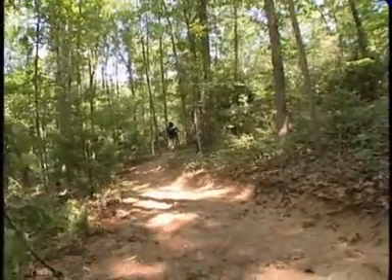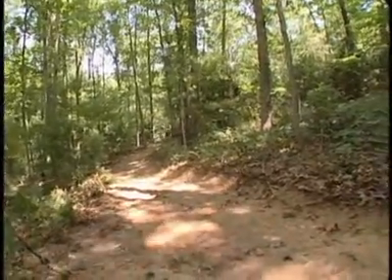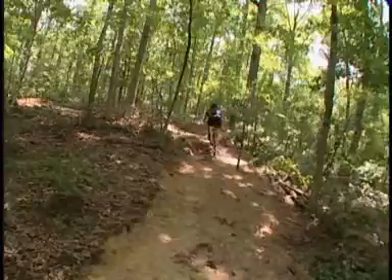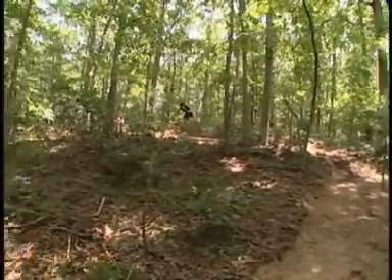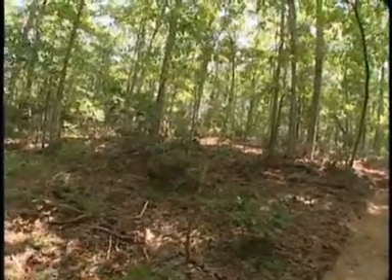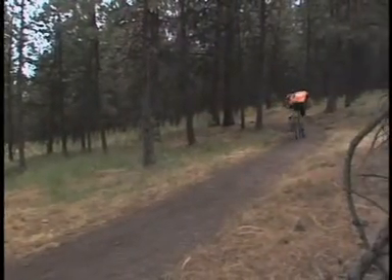Place grade reversals at both the beginning and the end of the turn. Because the climbing section lies directly in the fall line, the grade reversal above the turn is very critical to keep water off the trail. To prevent shortcutting, wrap the turn around large trees or boulders. These features of climbing turns will give you a free-flowing and sustainable trail that's fun to ride.